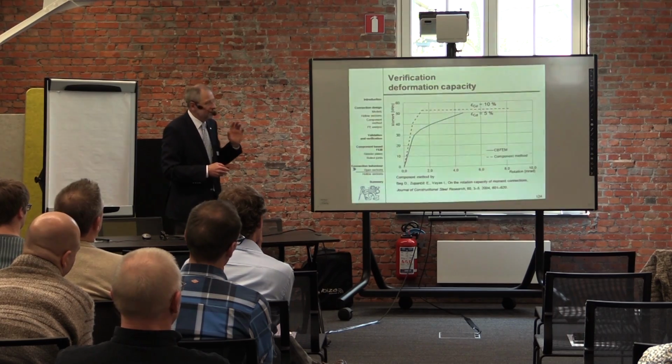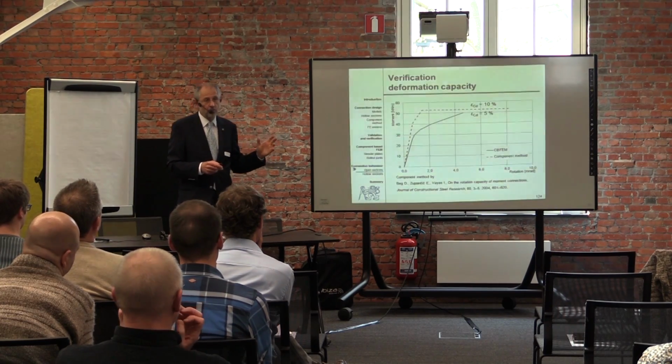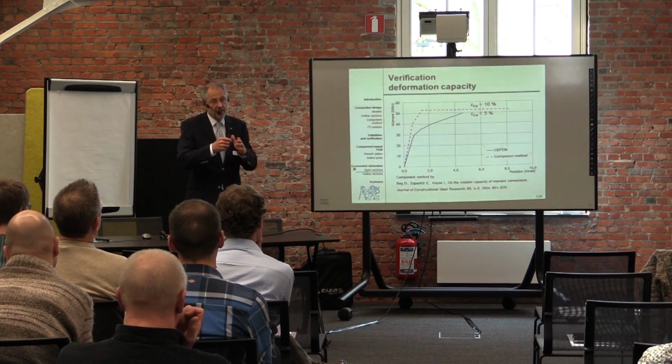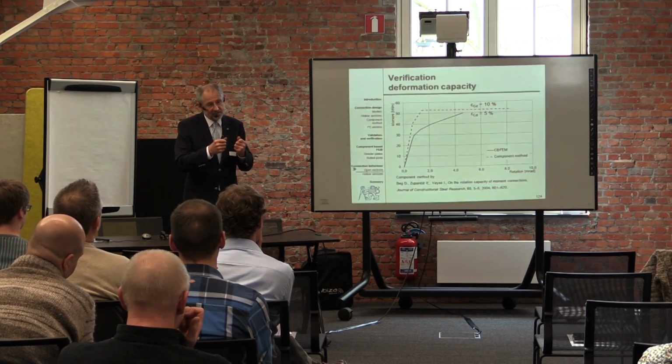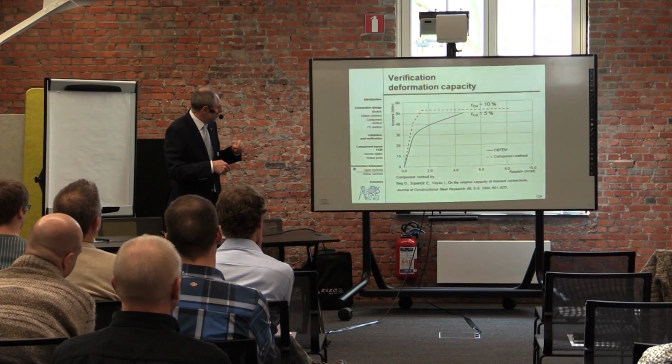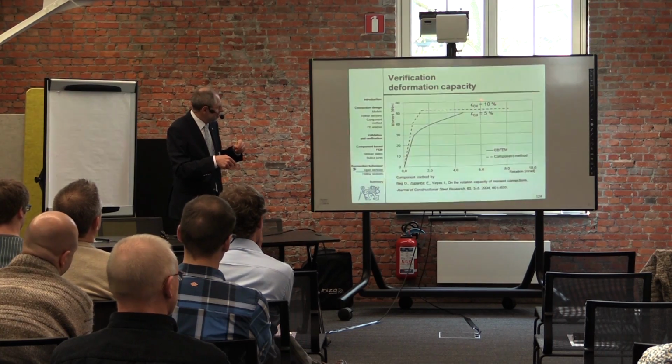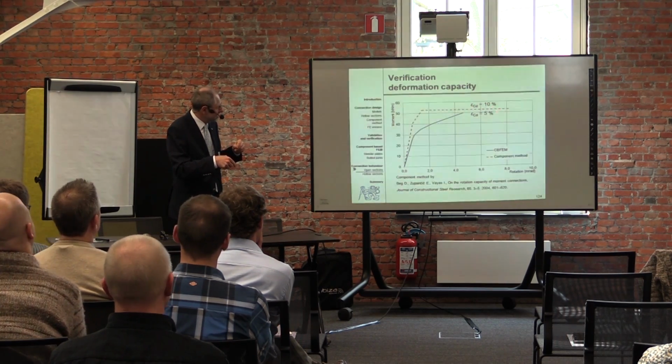And now the deformation capacity. Maybe you know this particular case is relatively brittle. The resistance is driven by the tensile resistance of the bolts in the second bolt row. And in Eurocode, we may calculate based on strain 10%.